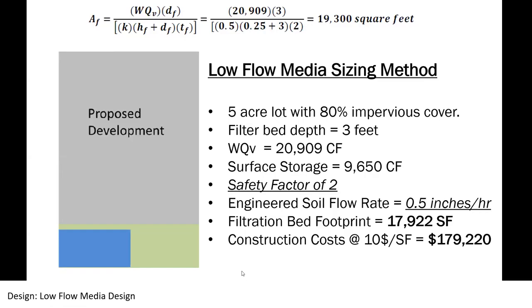And then what can local municipalities do when there are no compliance requirements or no post-construction ordinance and the bioswale needs maintenance? Really, that's going to come down to the owner. If there's no one really enforcing maintenance, then your system will probably sediment in and it'll probably work for a while, but depending on the design, it's only going to last so long. You're going to need some type of maintenance.